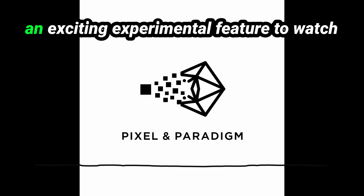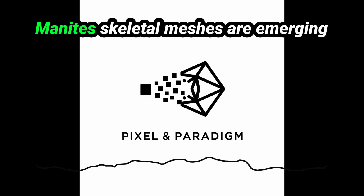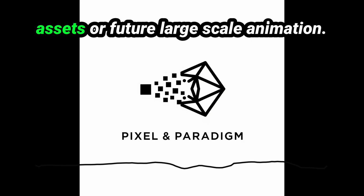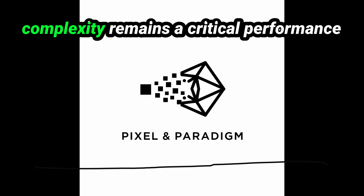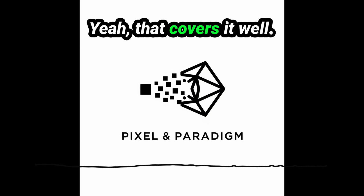Nanite tessellation is an exciting experimental feature to watch, with huge potential for surface detail. Nanite skeletal meshes are emerging and improving, potentially key for hero assets or future large-scale animation, but complex currently. And finally, don't forget to optimize shader complexity. It remains a critical performance factor alongside geometric cost. Yeah, that covers it well.